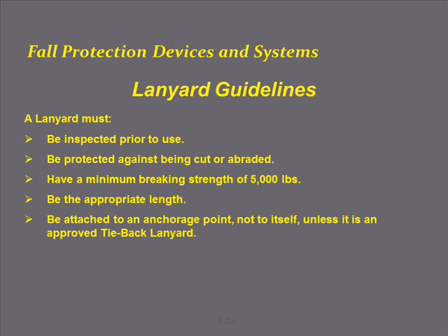Your lanyard has some very specific and important guidelines. A lanyard must be inspected prior to each use, be protected against being cut or abraded, have a minimum breaking strength of 5,000 pounds, be the appropriate length, and be attached to an anchorage point and not to itself, unless it's an approved tieback type lanyard.